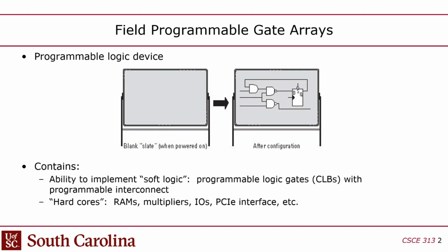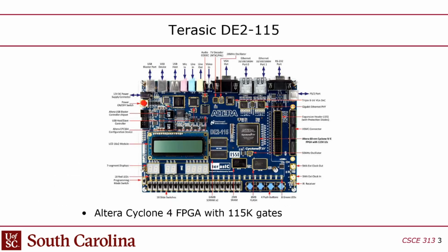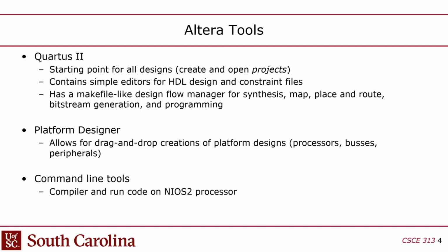FPGAs are the blank slate. You program them and they implement whatever logic you design for them. So they're a programmable logic device that when you turn them on, they're just a paperweight. But after you program them, they will behave like an arbitrary digital logic circuit as long as it fits on there. And we're using the Terasic DE2. And we're using Quartus II, which is the main IDE, and Platform Designer, which is another IDE that allows you to use the IP blocks and assemble the system. And then the command line tools for programming.